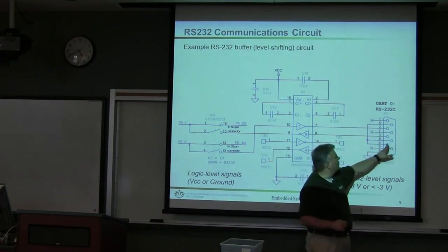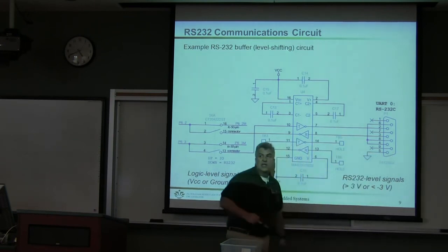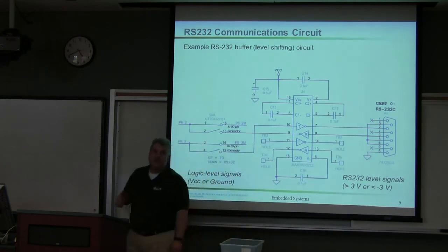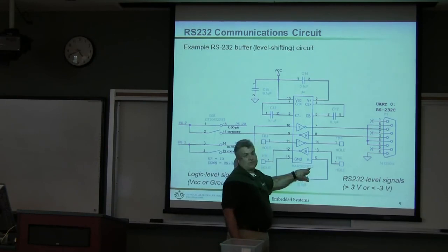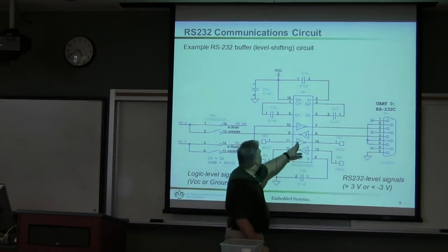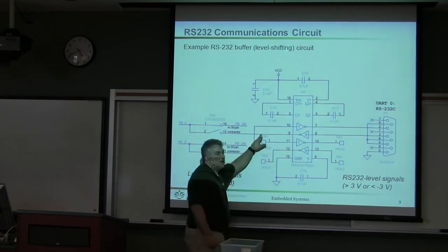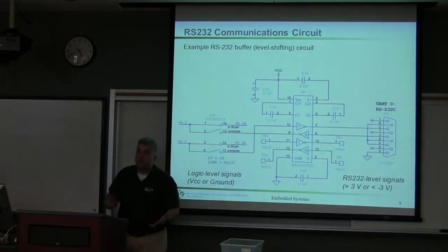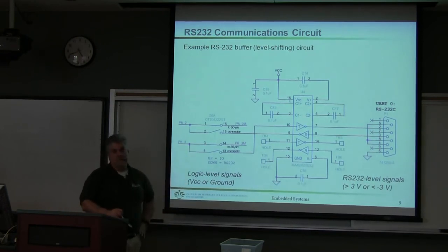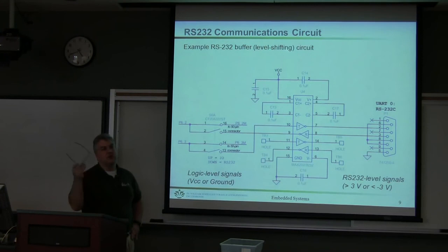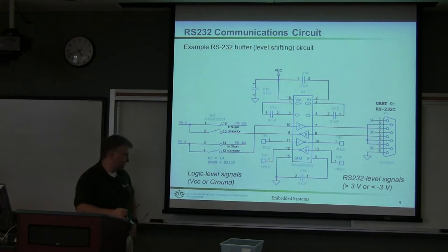But you have to make sure your voltage level is going to be appropriate for the PC to read. Now at the other end, the PC is going to have a 232 chip as well, which will convert the signal it's receiving into a voltage level that the computer at the other end can actually work with. Your typical PCs will have an internal bus, and it'll probably work somewhere between 3.3 volts and 5 volts at that end.